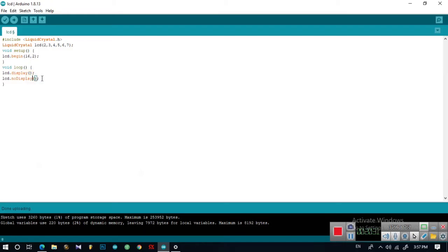You should turn off the display first and then use this for turning on the display again. It's not like lcd.clear that clears everything on the LCD screen. It restores the text and the cursor that was on the display, and just displays it and stops displaying it. It does nothing to the text and the cursor on the LCD. It saves that.